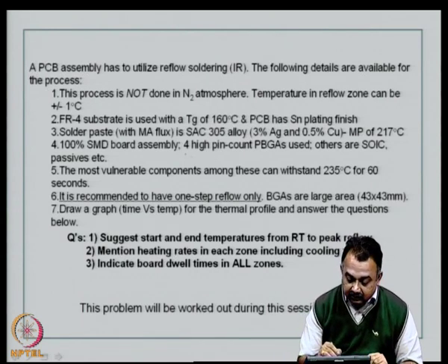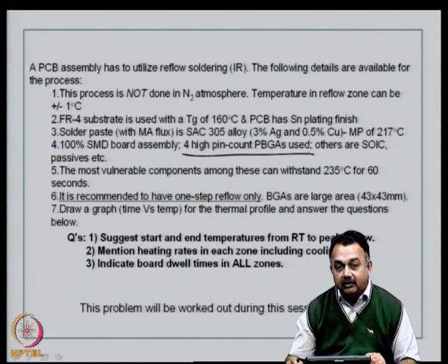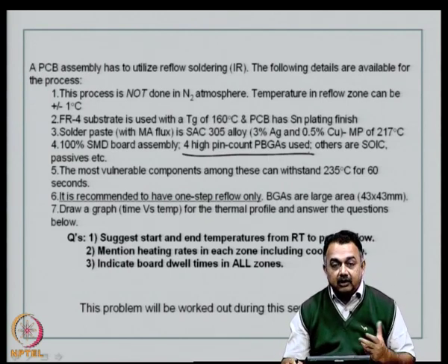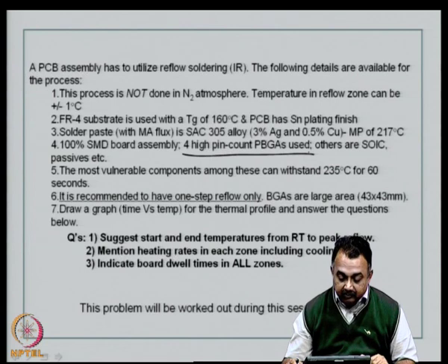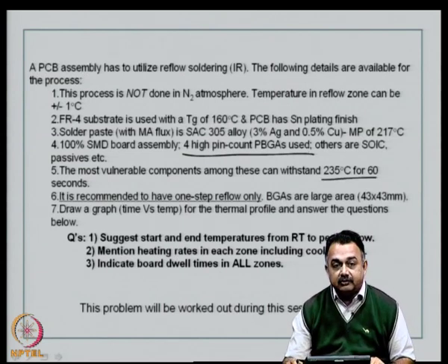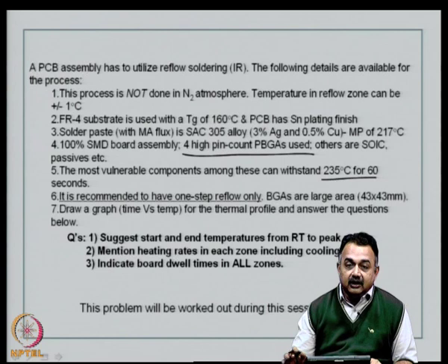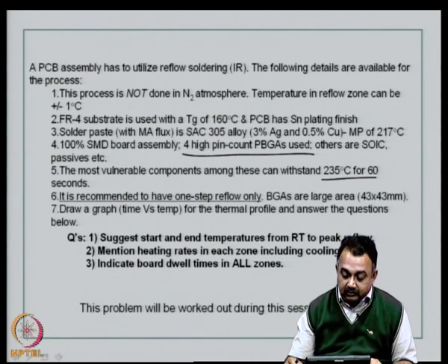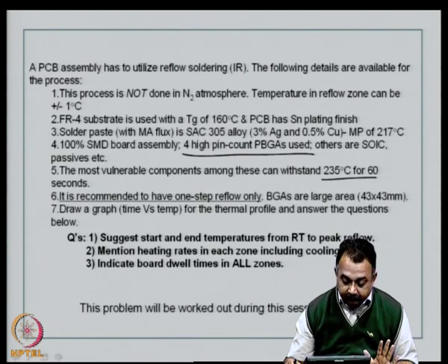The reason why I am giving this is that in your board, in your system, you could encounter such day to day problems. The most vulnerable component among the entire components that are being used in this design can withstand 235 degrees centigrade for 60 seconds only. So, that clearly defines your peak reflow zone residence time. It is recommended to have a one step reflow only.